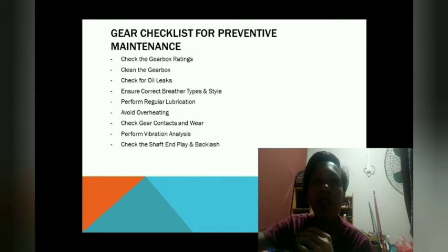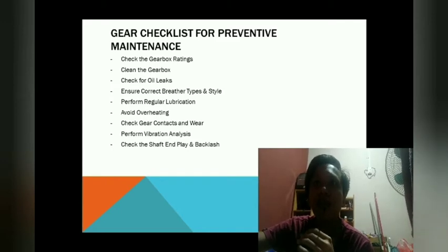Next, perform regular lubrication. We need a proper and timely lubrication. By proper lubrication, it means that it should adhere to the grade, type, and quantity specification of the manufacturer.